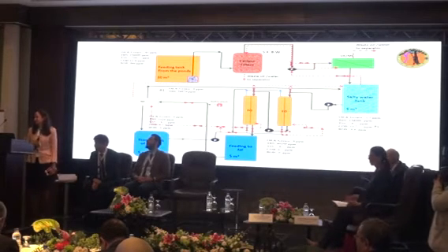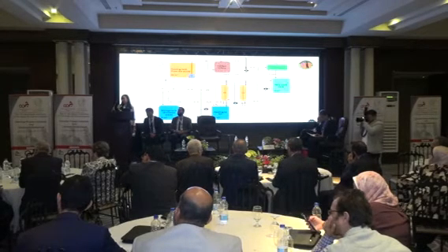Thank you for your presentation. It's very good. It's better to use this water again, injected to the well. But my question here is, why should you remove TDS? For oil you should remove the oil, correct. But for TDS, this is slightly strange for me, because you put anti-scaling and re-inject it again to the well. That's our normal procedure in that matter.